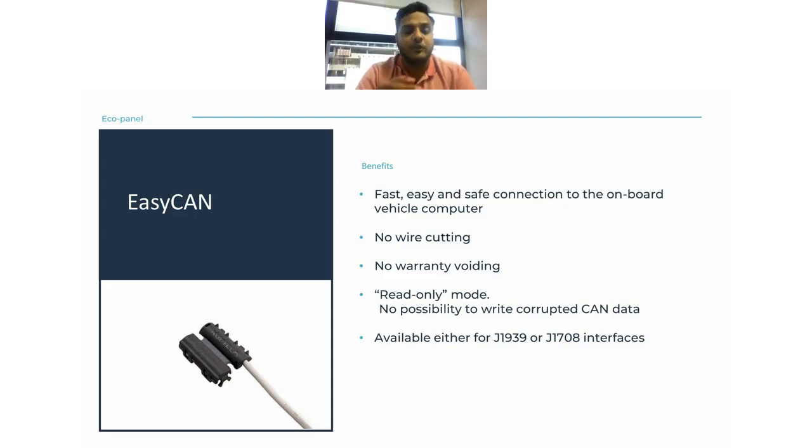Basically, you pass the CAN lines through this sensor, close it, and read the data onto the device. Another good thing is that it won't let the device send any commands to the CAN network of the vehicle. Once you install these devices, turn the vehicle off and lock it, the telematics device may send a ping or a handshake to the CAN network.